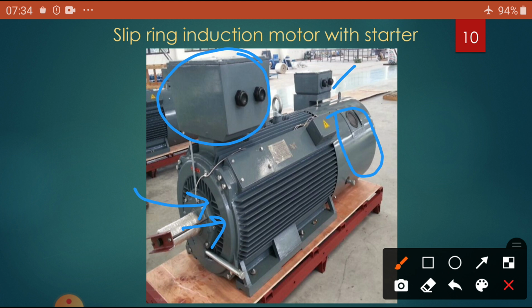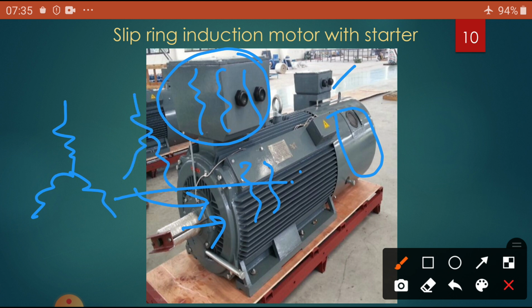How are the slip rings connected with the resistance connected externally, and whether our motor stator winding is connected in delta or star? Let us assume this stator winding is connected in star. Then our rotor is also connected in star. Then how are we going to connect the resistance in the circuit?